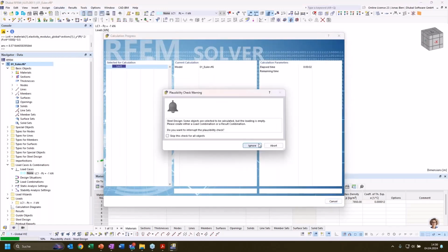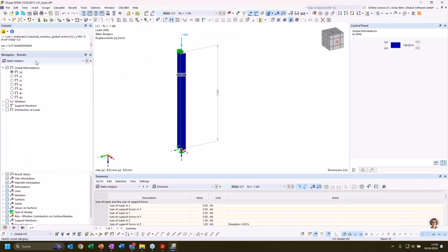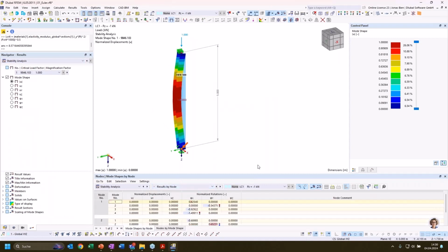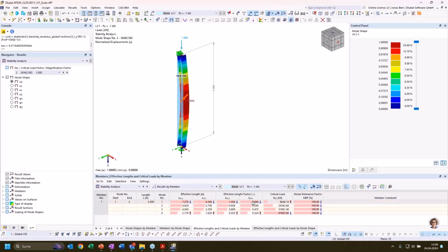Here it's not so obvious what the buckling length for our equivalent member check would be. Of course, we could look into textbooks that have these cases covered, but also here we can use the structural stability analysis to evaluate the effective buckling length factor. And as we expected, it is between 1 and 0.7.